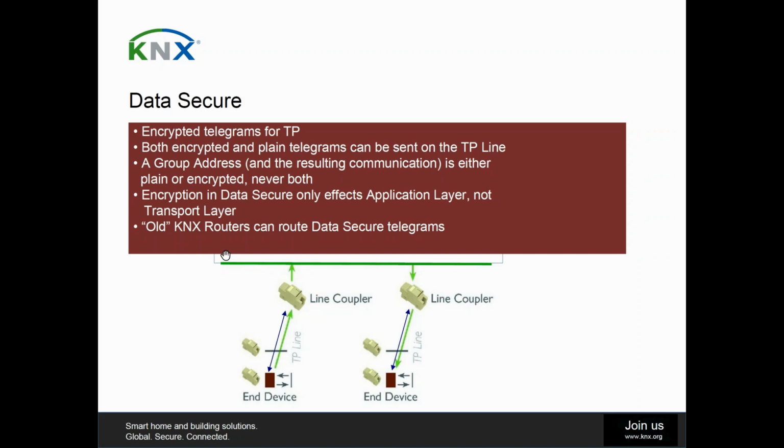So, for example, if you have a pattern of four zeros in your original data, then there would be no four, let us say, AA in the encrypted data. So that is very important. And for now, it is AES 128, which really has this property, and therefore now all telegrams in secure mode are encrypted with this AES 128.